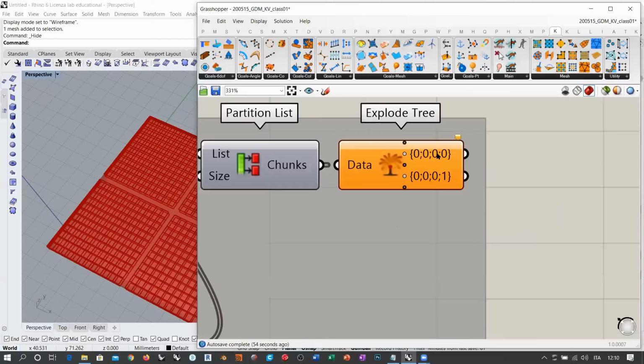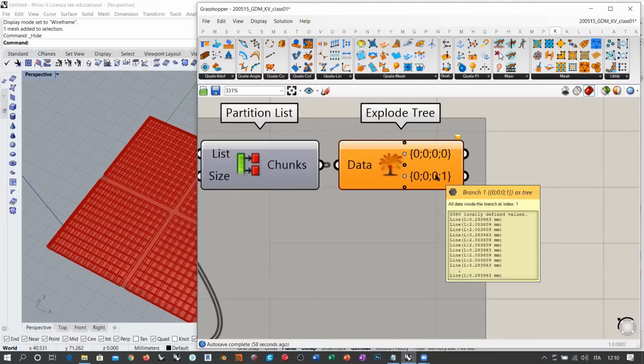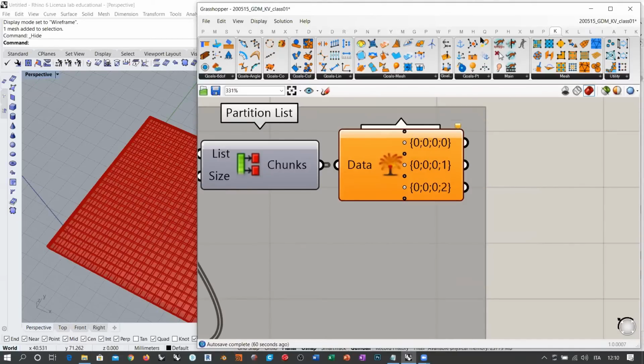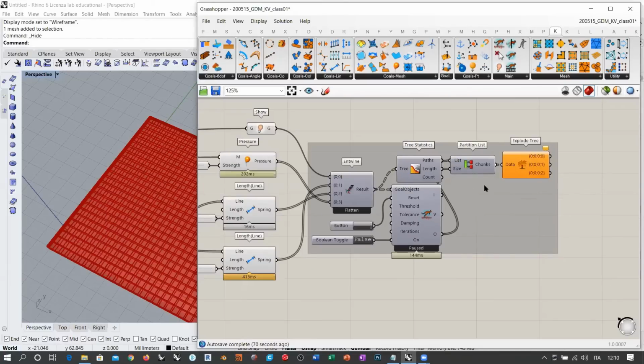But anyway, you see that now we have the mesh and the elastic edges here, and these are the rigid edges. Somebody knows it? Let me see. Cluster? No, no. Cluster is a way in Grasshopper to group components inside one single block, one single node, but it always works inside your script. So if I create a cluster with this inside this definition, this cluster will not be available in a new script. While this plugin that I'm saying is basically a Grasshopper component where you store a group of components and you have it available inside each script that you create.